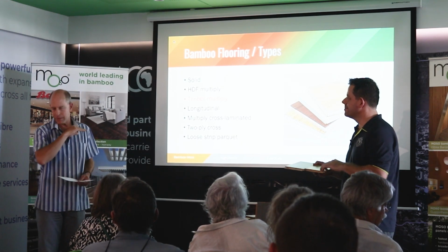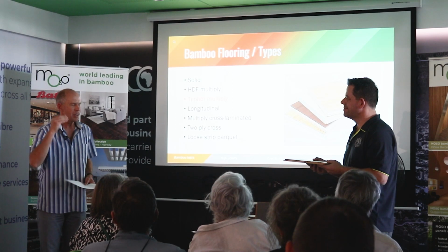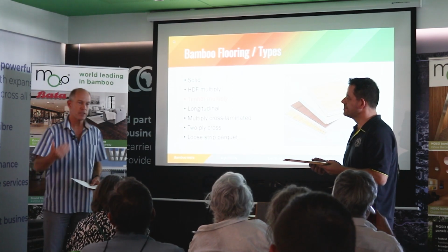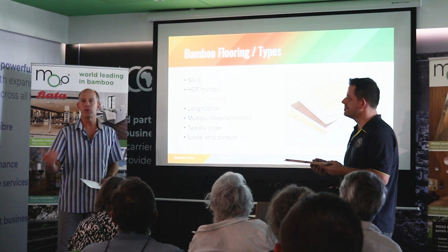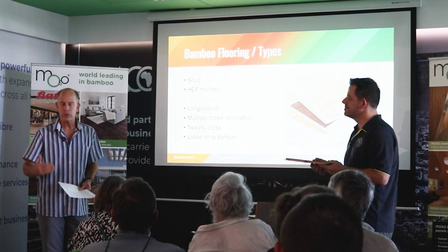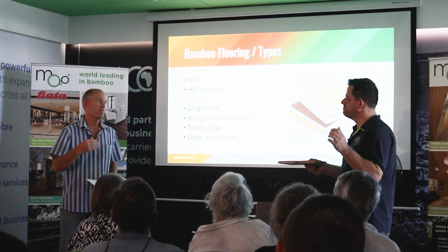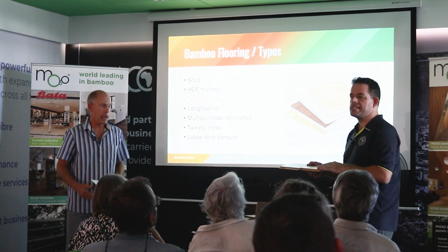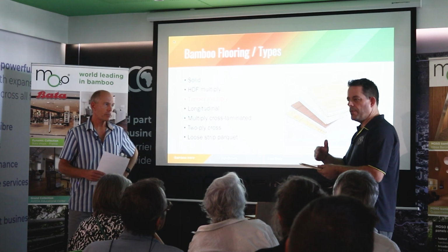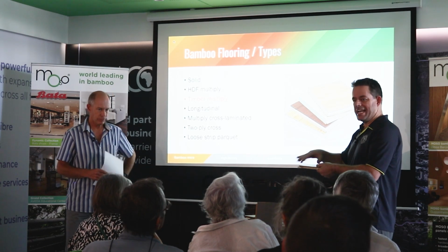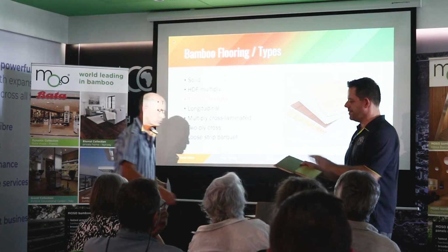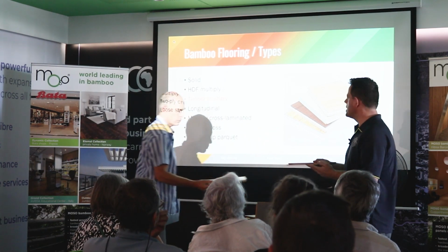The flavor of the month, virtually everybody now sells engineered timber flooring for the reason that it's much more stable. It doesn't give the issues that solid timber flooring and solid bamboo flooring can give in terms of reaction mainly to moisture. Also it allows us to have a wider plank. So with the stability of the cross lamination underneath, we can go for a wider, longer lamella on the surface, which really, we all know we want bigger, we want longer kind of thing. That's where that offers a lot of value.